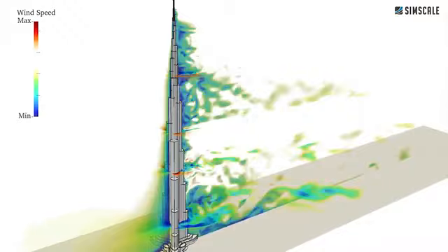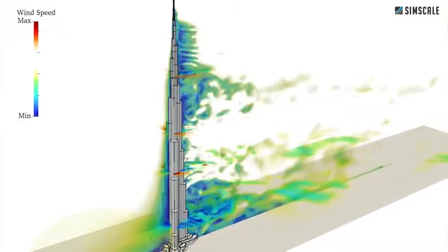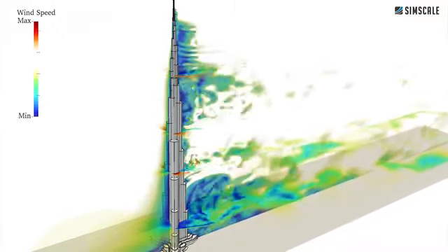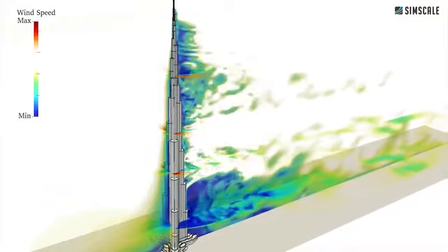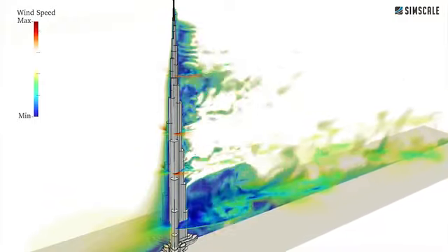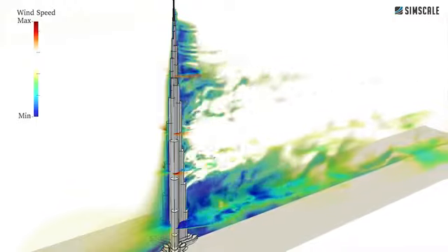Wind loads on buildings. We can see the main effects of the structure optimization in this animation that shows the flow physics at 3 different cross sections along the height. Close to the base height level, the area is the largest, and so is the wake behind the structure. But the corner softening helps to avoid strong vortexes.